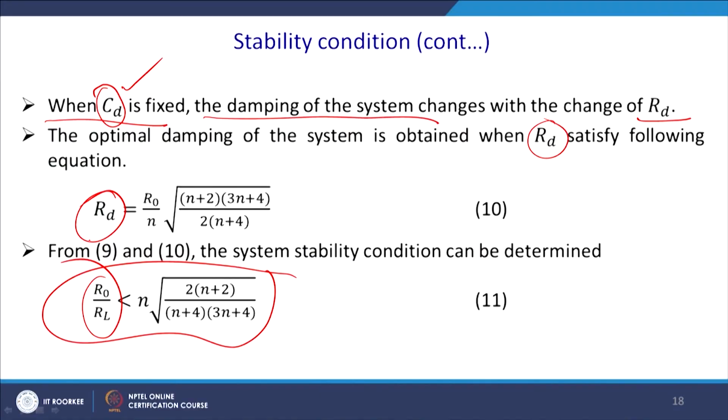So, the n value is 100, and accordingly you will have an R d, and thus you come to the conclusions, and you require to design properly what the value should be. Please note that this capacitor C d should not interfere, and it should be around 50 to 100 times higher than the value of the filter capacitor C, then only this will work fine.